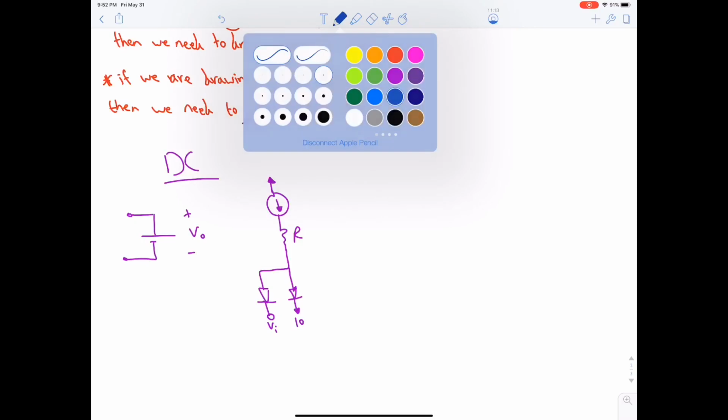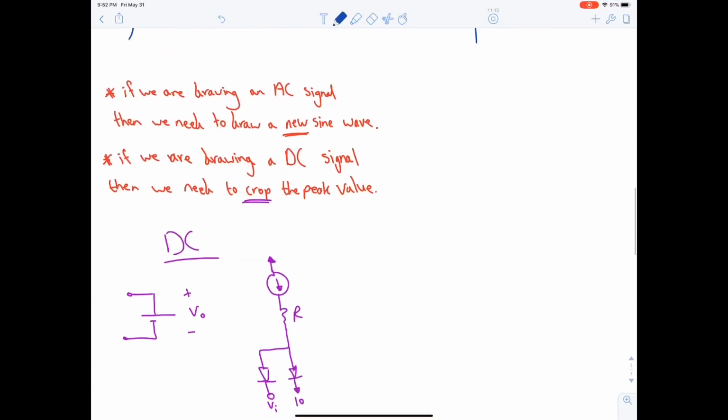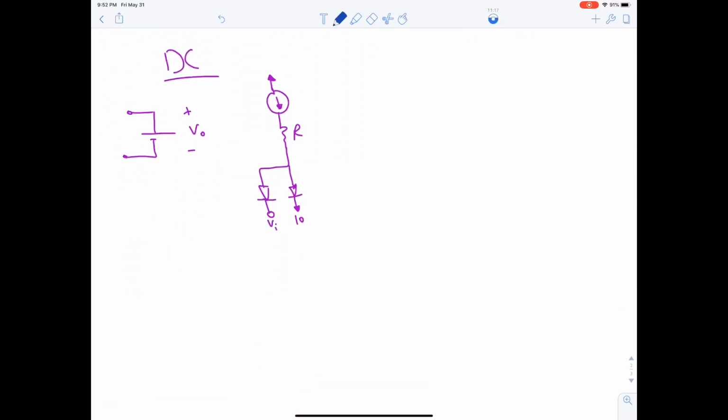Okay, moving on. Now, in selecting diodes for rectifier designs, two important parameters must be specified: the current the diode is expected to conduct and the peak inverse voltage, PIV, that the diode must be able to withstand without breakdown, determined by the largest reverse voltage that is expected to appear across the diode.